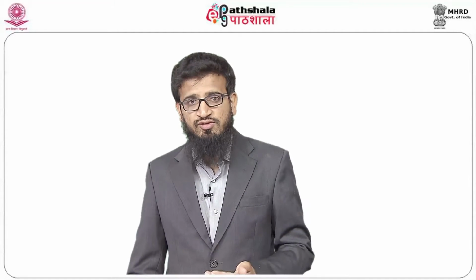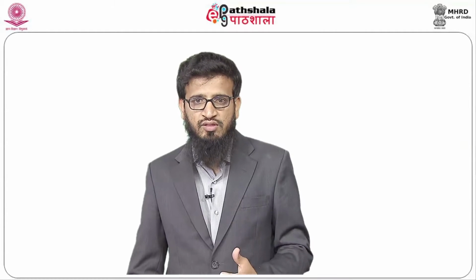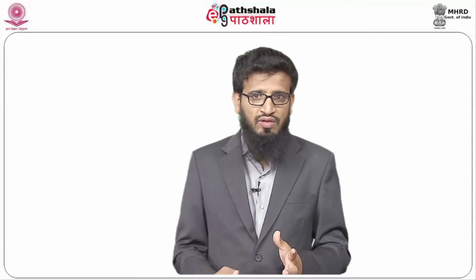But when you look at the glass products, with the embodied energy compared to the savings, hardly 20% of that can be reused. So, though glass is less compared to the total embodied energy, it cannot be reused. This becomes a very dicey situation for designers, what to pick and what to leave. So, it is a wise decision, or clever designers will choose what can be used and reduce the embodied energy, and at the same time use things which can be recycled, because at the end of the life of any building, the materials should be recycled. As we spoke about adaptability in the initial stages, this is what it means.